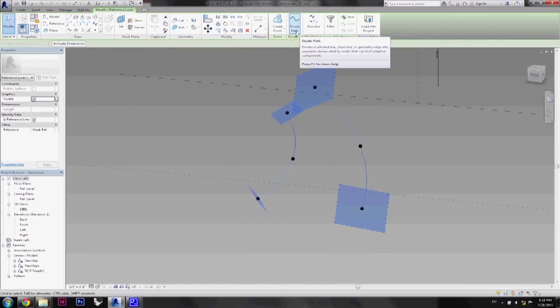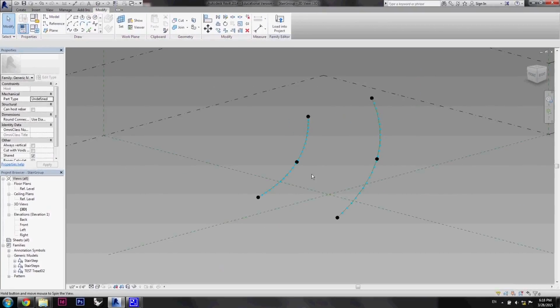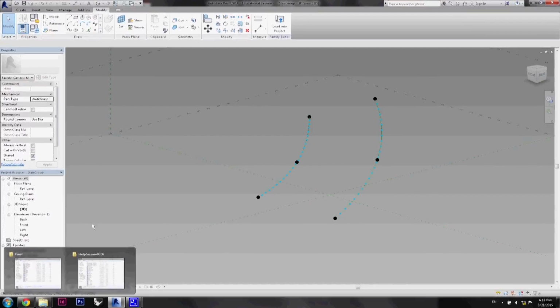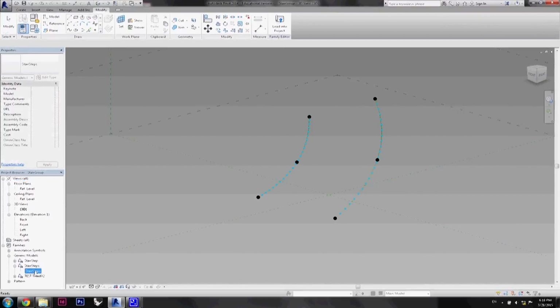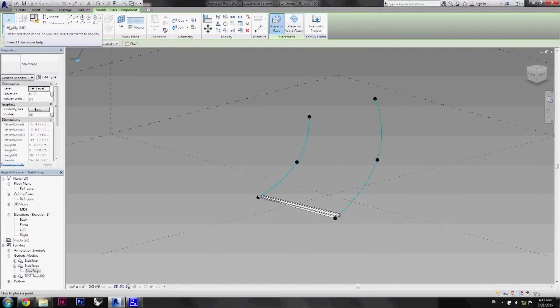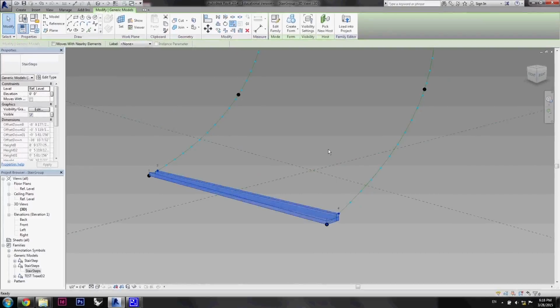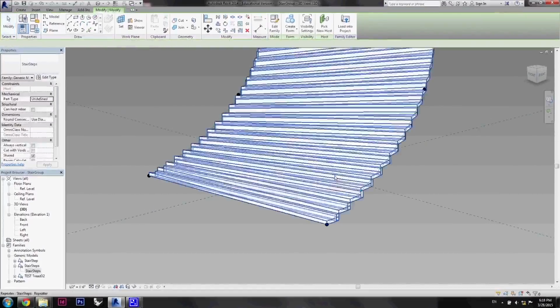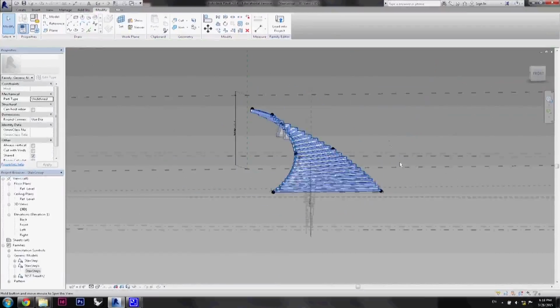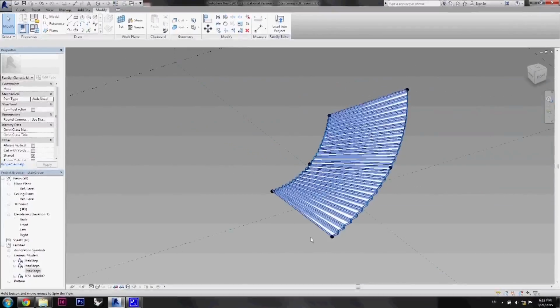Divide path. And the floor height is like 12 feet. So we just build like 24 stair steps, which is appropriate. And yeah, drag the adaptive component into the project, with the right order of points 1, 2, 3, 4, and then repeat. Now we have the curved stair steps, and we are going to do the railings next.